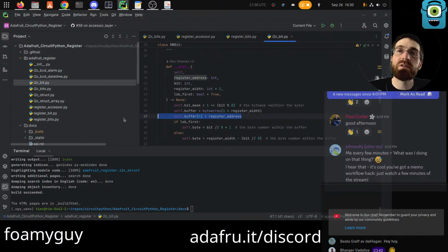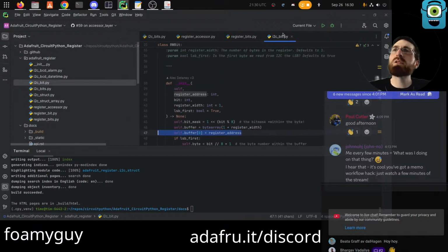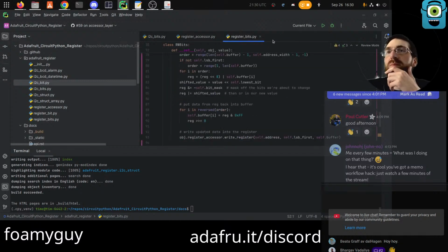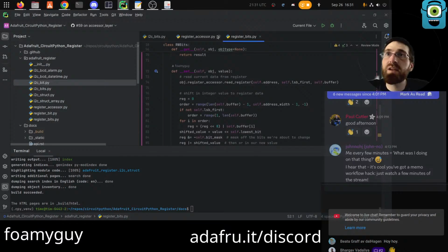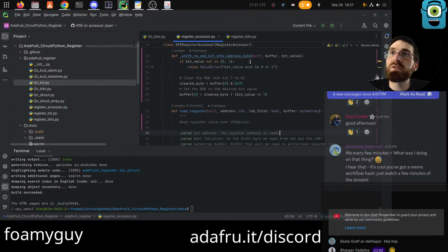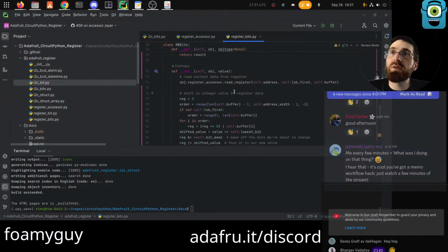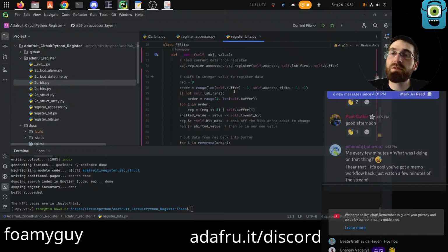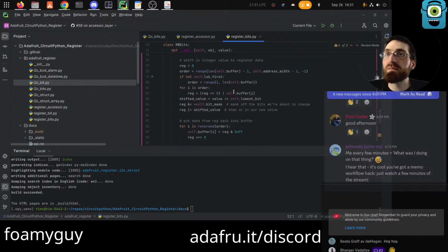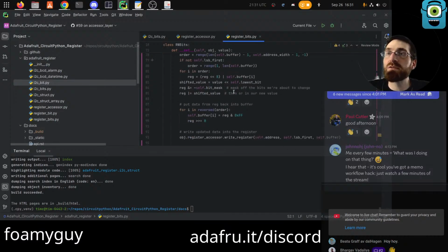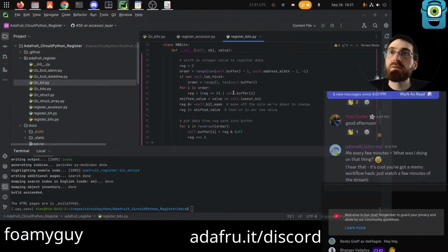Maybe it came from the register SPI, which is what I started from. Maybe that one was actually using it. I'm not sure. But now it's not being used, and having it do that would actually be bad because it would break the multi-byte address, since we'd clobber the byte at index 1 by randomly setting it.